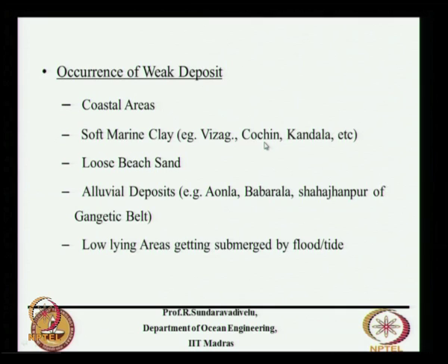One of the problems of soft marine clay is what is known as negative skin friction. Instead of the pile taking the load from the substructure, because of the settlement of the soil being more than the settlement of the pile, the pile will take additional loads, and that is called negative skin friction. That means the total capacity will come down.